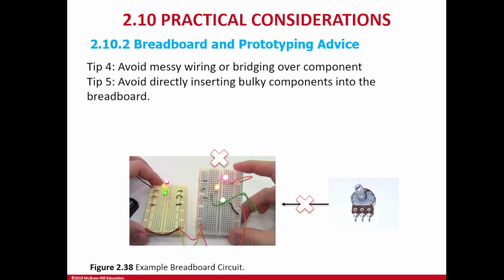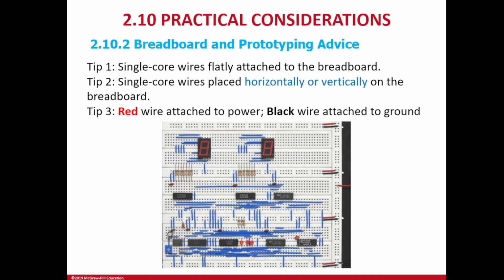Don't bridge over the component. For example, this is not correct, because this is a simple LED. But how about an IC? The IC occupies some space, and it's more difficult to detach those cables for replacing the IC. So don't bridge over the component.